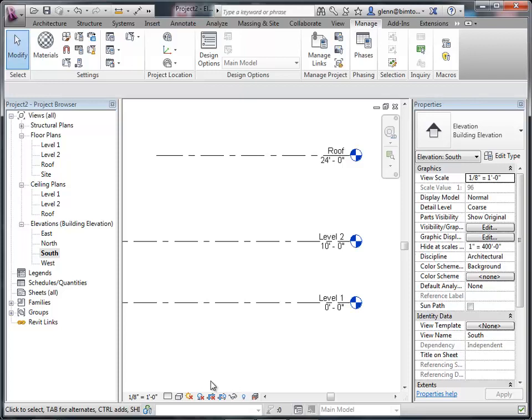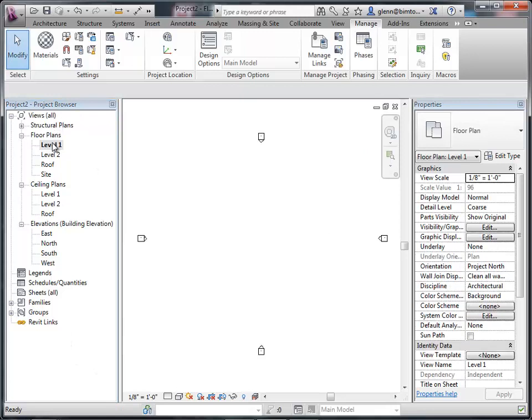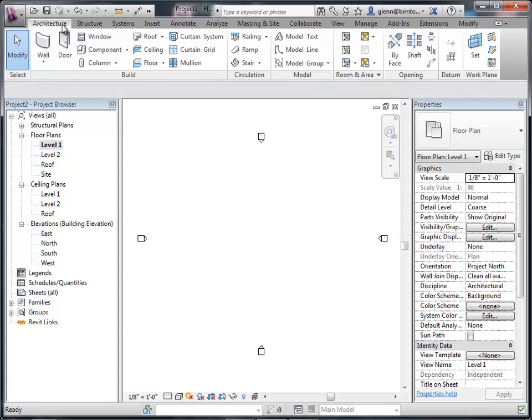Okay, as we're working with walls, let's go ahead and switch back over to the floor plan view and just kind of talk about some basic walls and how we do it. The main tools that we're going to work with as we get started are going to show up either on the Architecture tab if you're in Revit 2013, or on the Home tab if you're in Revit Architecture 2012. But on that you'll find walls, doors, windows, roofs, floors, all the biggies. We're going to start with the envelope, but all right up top.